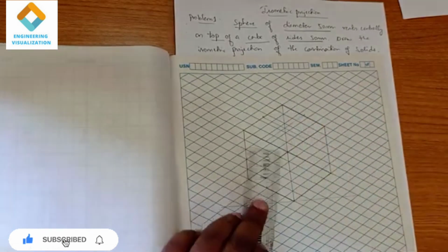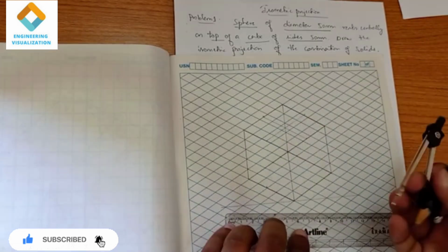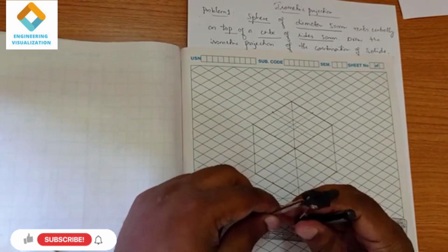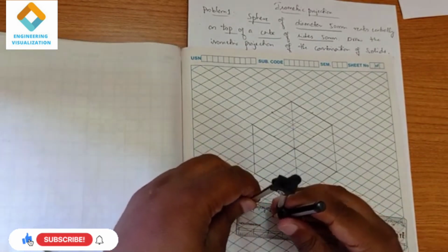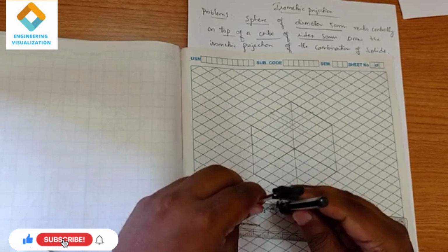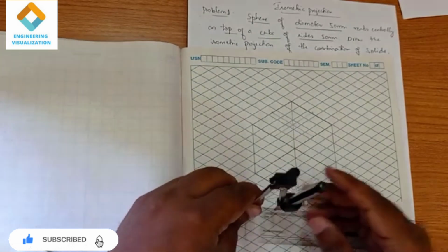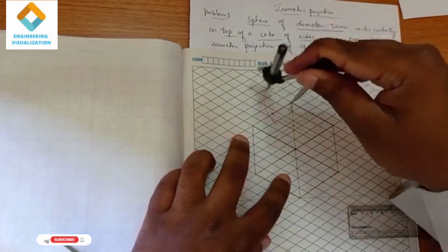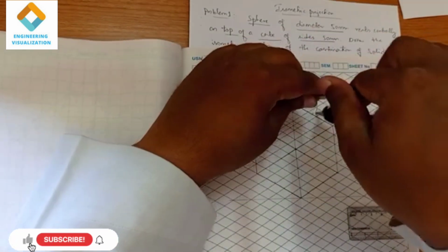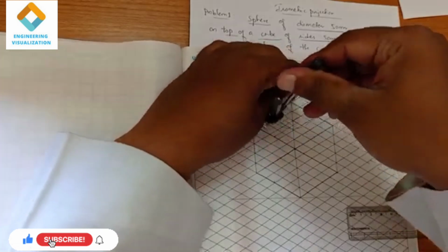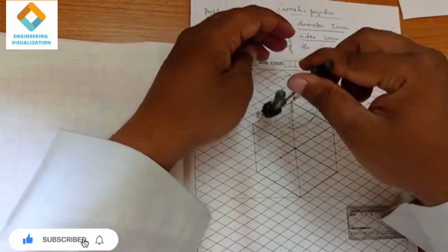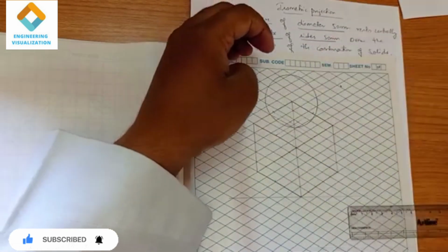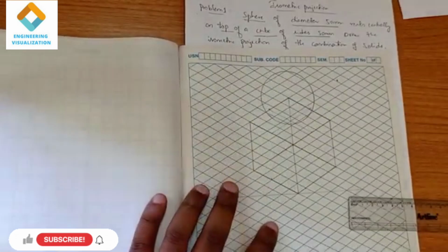And here a sphere will be drawn with the actual scale. Sphere is the only solid which will be drawn with the actual scale. Except for a sphere, all the solids will be drawn with the isometric scale. Remember it. Always remember it, because if we incline a sphere at whatever angle, 30, 40 or 50 degrees, you will get the same circular shape. There is no change in the shape in the case of a sphere. So remember, a sphere will be drawn with the actual scale.